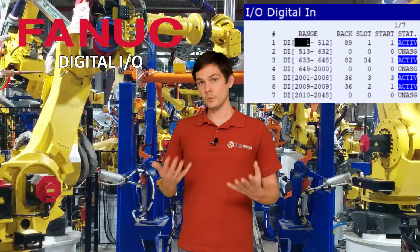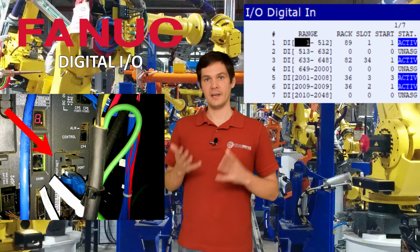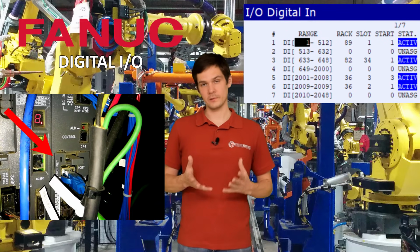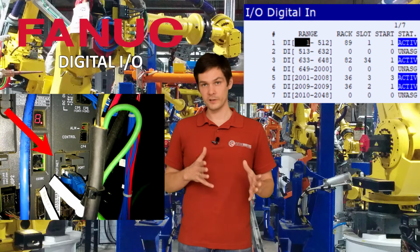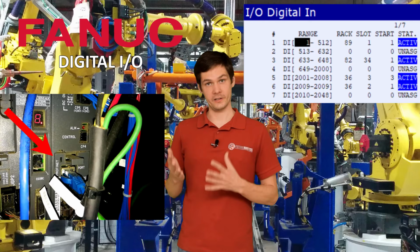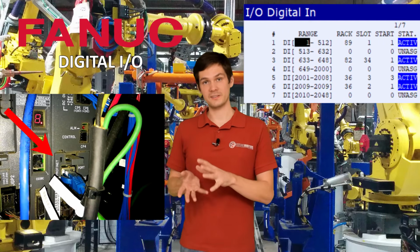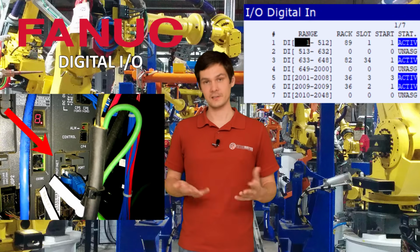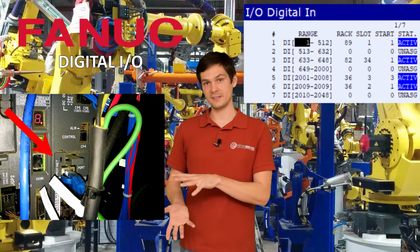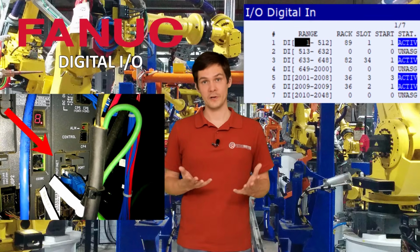When you know what type of communication you're using, you can locate the card on your robot. I've shown you in one of the previous videos, when I opened the robot cabinet and talked a little bit about what's where, you can see a Profinet card in there. So you know that you have that card in there, right? And you know that you want to send those outputs through those cards to the PLC or other devices. Great, so we know where the card is located. Now we have to tell it to the robot because he doesn't know, right?